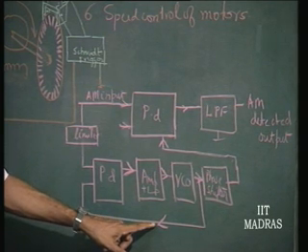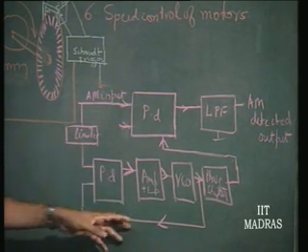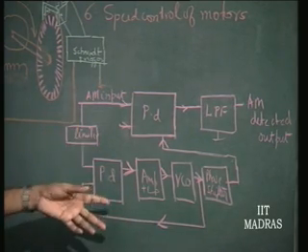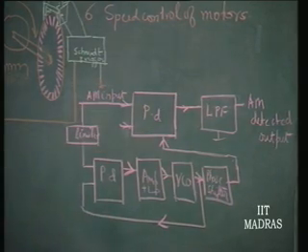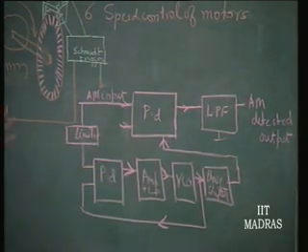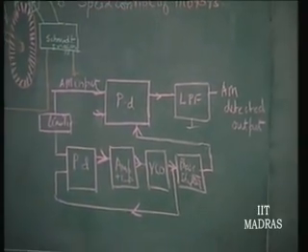at a phase shift of 90 degrees if it is originally tuned to the carrier, right. Now, if you use the phase shifted carrier itself for multiplication, you will not get an average, because if this is cos, this will be sine and the average will not be there.